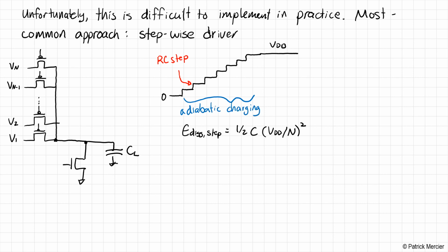Now, once we're at VDD, we have a couple different options we can take here. We can take that energy in VDD and we can just dump it back to ground through that NMOS transistor, something like this. Okay, so build something like, I don't know, a staircase at the end of the first level of Super Mario World on NES. But it turns out that there's actually something smarter we can do here. Rather than do that, I'm going to erase that, we can actually go ahead and step down. Now this should be technically drawn symmetric to the other side there. I probably don't have that totally correct here. But we could do something like this.